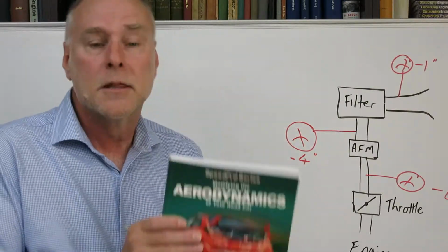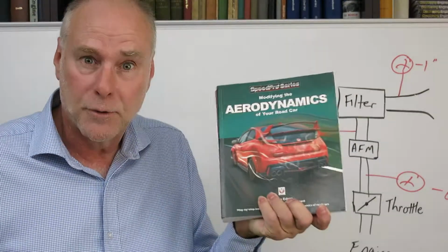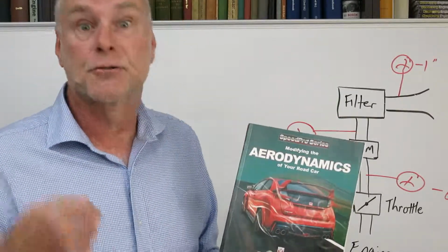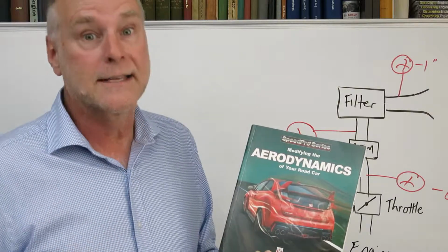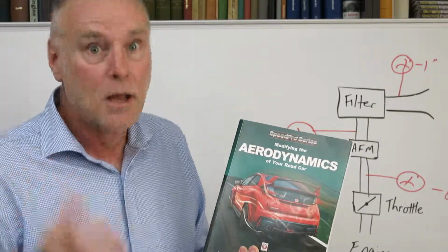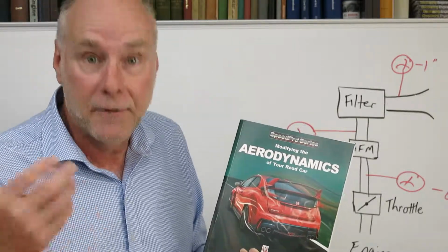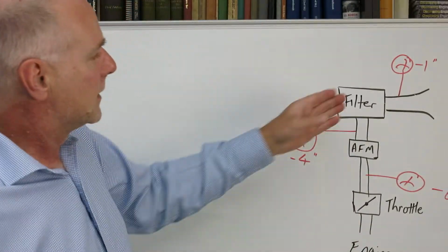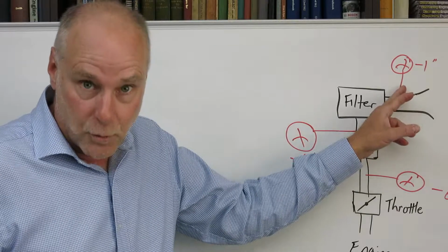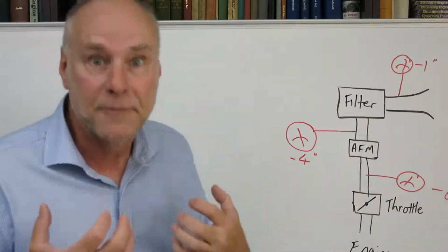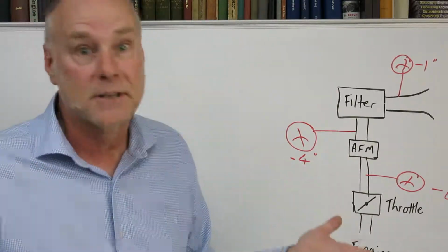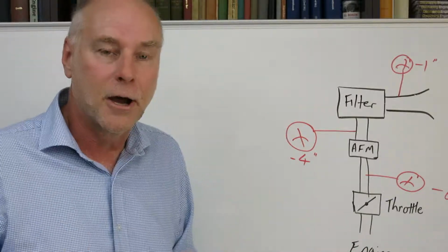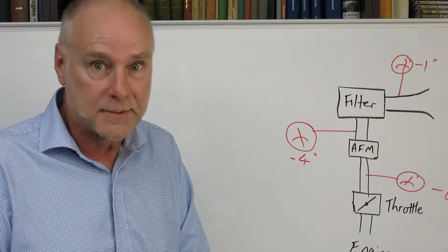And to remind you, the book's called Modifying the Aerodynamics of Your Road Car, and I'll have a complete chapter where I talk not only about streamlining, aerodynamically optimizing the intake system to the engine, I also talk about picking up air at an aerodynamically high pressure point. I've covered that in another video, but typically you can get a few inches of water pressure back from the aerodynamic force of the air being pushed in. So for example, more than make up for the restriction of the air filter. But that's another video, but it is also covered in that chapter in the book.